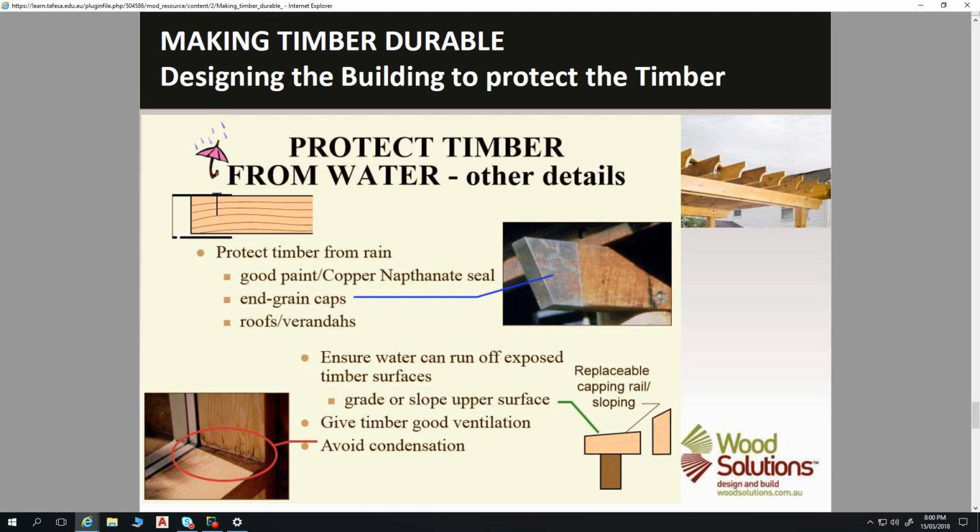Yeah, so a poorly constructed or poorly thought out pergola will have that, and that's why you typically see this detail there. And that detail may be this type of end, or it might be that, or it might be, let's say, the other one, really long slope. Various ways of doing it, but it's to ensure that your drips drip off the end better.